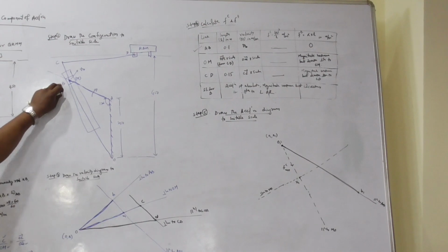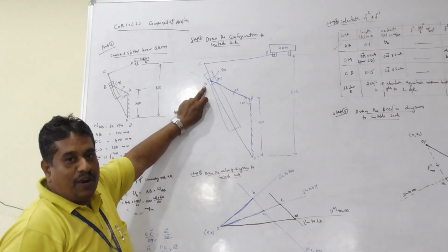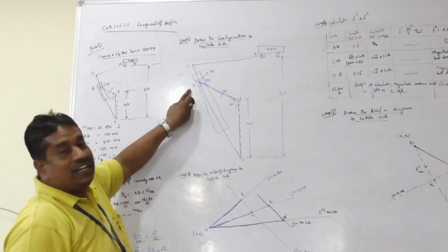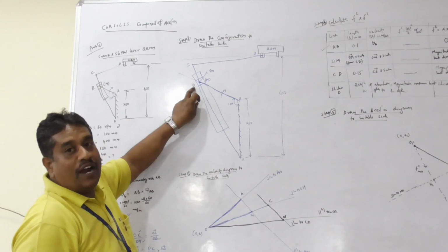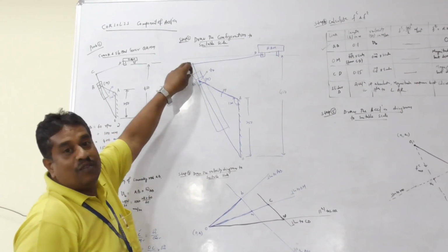Now consider point B, the sliding point B or a moving point B, which moves along an oscillating link, and at the given instant of time, this moving point coincides with the fixed point M on the same link OC.